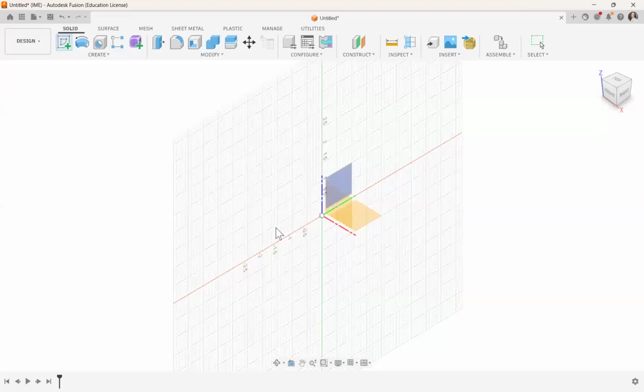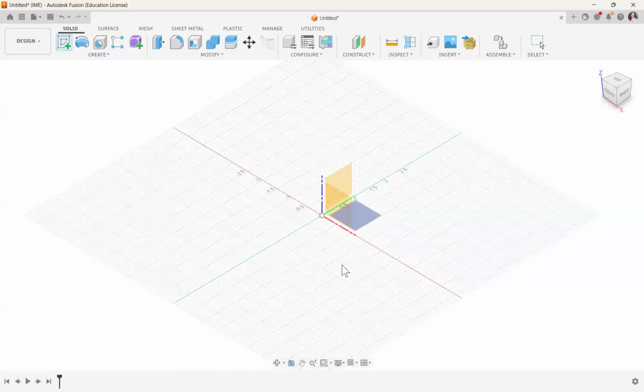So you've got all these different planes. You've got the XZ plane, the YZ plane, and the XY plane. This is very important. You need to select the XY plane, which is the one that I have highlighted in gray here on the screen, because the machine, the Laguna that you're going to machine on, has the same configuration as this Cartesian plane.